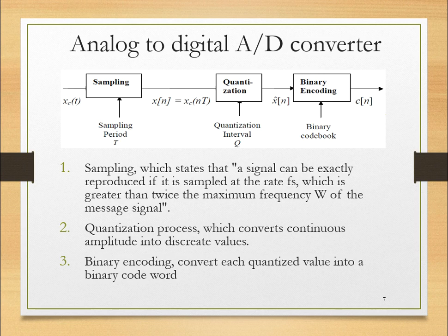Sampling, what do I mean by sampling? Basically, without confining ourselves to a textbook definition, any signal has the x-axis, which represents the time, and the y-axis, which represents the amplitude of the signal or the power. Sampling deals with the time axis. Instead of taking all the values on the time axis, you just take points, and these points we call samples.